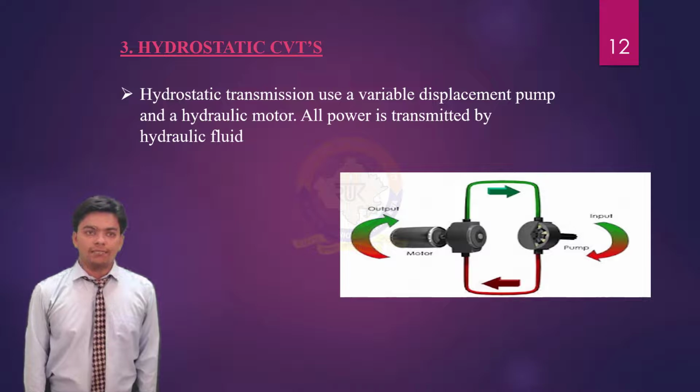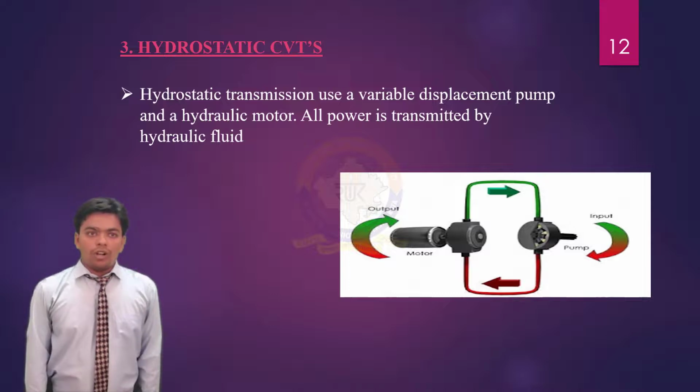Hydrostatic CVT. Hydrostatic CVTs use a variable displacement pump and a hydraulic motor. All power is transmitted by hydraulic fluid.